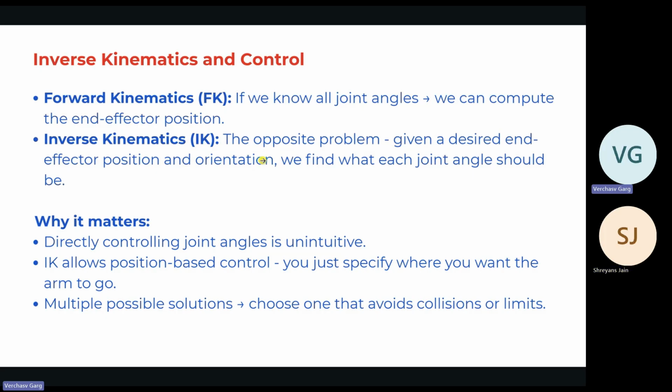Inverse kinematics is more important than forward kinematics, because there are several possible solutions to inverse kinematics, but we have to select one that fits all the required constraints, such as collision constraints or workspace limitations as well. For that, we have certain modules for solving inverse kinematics and mathematical equations. Now I would like Nitya sir to explain inverse kinematics.